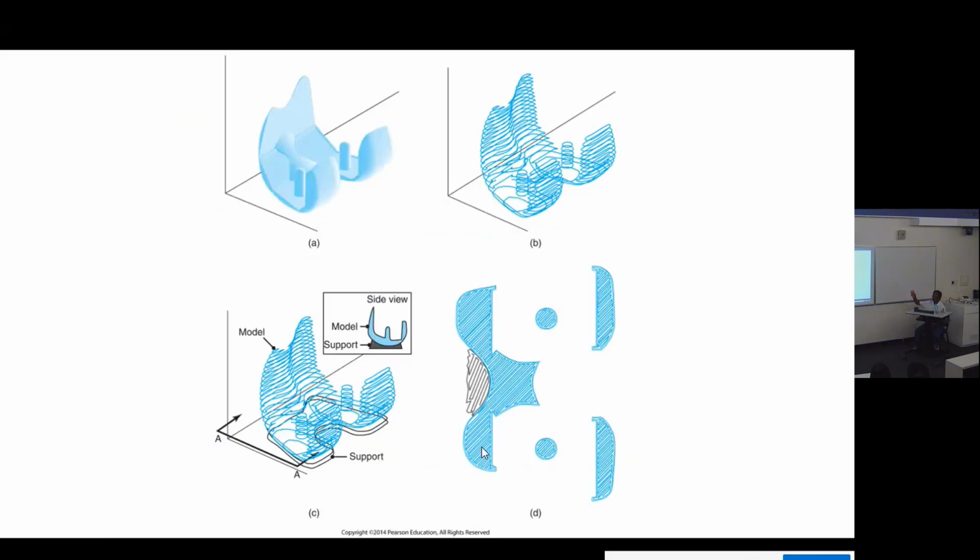So these will take probably weeks or even months sometimes, if it's a large part. It may not require any processing, but if it is a large part, then it might need a heat treatment to reduce the residual stresses. So one of the problems with this is the time it takes to produce the parts.